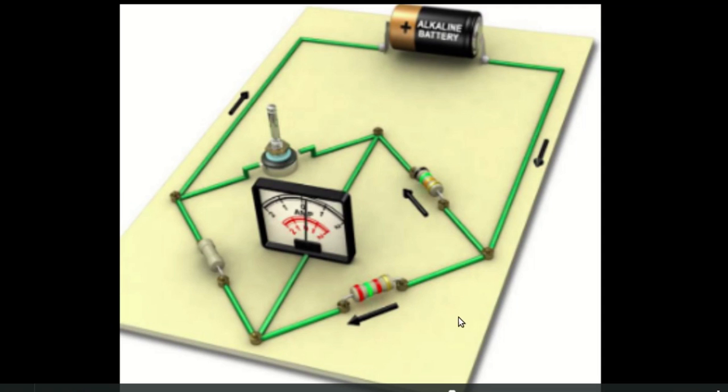This is the animation of the connected Wheatstone bridge. So here this is the battery or the voltage supply. This is the flowing current through this, and this arrangement is called Wheatstone bridge. So this Wheatstone bridge consists of 1, 2, 3 and 4 resistances, out of which 1 and 2 are known resistances, and we have to find out this unknown resistance using this variable resistance. Variable resistance means we can change the resistor using the knob.